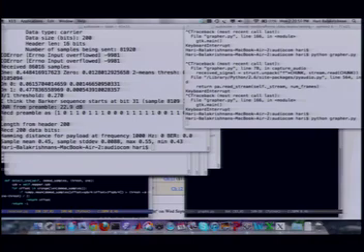Now, one of the things you would want to do is figure out why, when you don't get a preamble. Usually it's a sign that either some samples are being lost because the audio hardware isn't able to cope with it, and the documentation describes how you deal with that problem. Or it means that the sampling rate is too high, and maybe something's running on your computer, I don't know, you have some video going on in the background, and it's not keeping up to read at 48,000 hertz. Or it's a sign that the signal-to-noise ratio is too low. Maybe you're in a very crowded location, or maybe the volume is too low. So those are usually the ways in which you go about fixing this problem with the preamble.